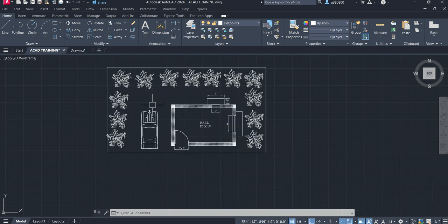Now just the change of layers first. So select all the trees first, or any other thing, it's up to you. It's not very specific that you have to use the trees only. Once you have selected the particular objects of the same layer which you want to put in the same layer, select only those things.